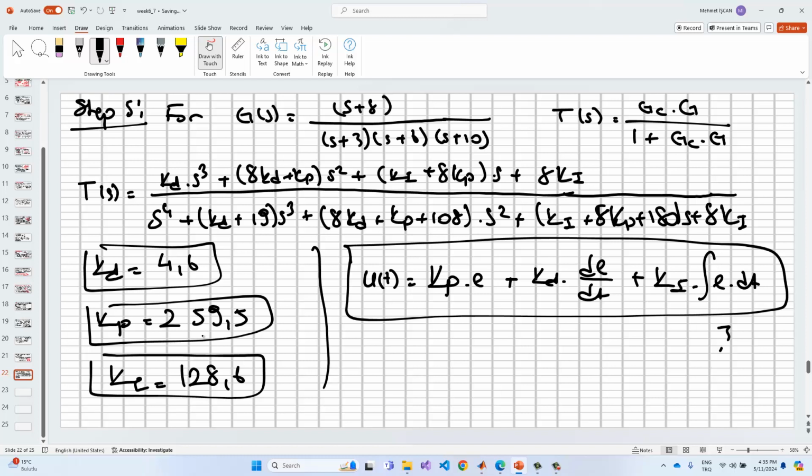So that's all. This is the PID controller design based on the root locus. But in lab 3 we have different design techniques, the pole placement techniques, because we can reach the whole characteristic equation coefficients, and then we can set Kd, Kp, Ki to different values of these terms. But just remember that if you want to design the PID controller based on a second order approximation, then we can utilize the root locus technique just like done in this lesson.